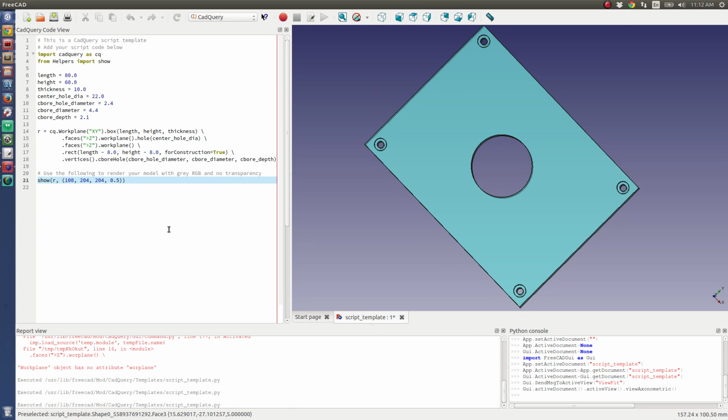As I say, it kind of shows you some of the core concepts, like being able to tell CadQuery to do something with multiple objects, and it just kind of iterates through and does something for each of them. Selecting faces, that is a huge help. And one of the really great things about CadQuery is these selectors, the concept of selectors.